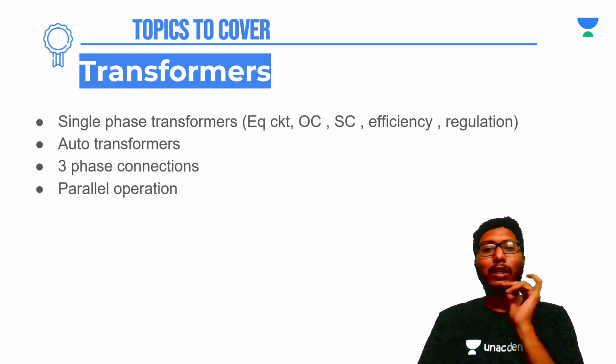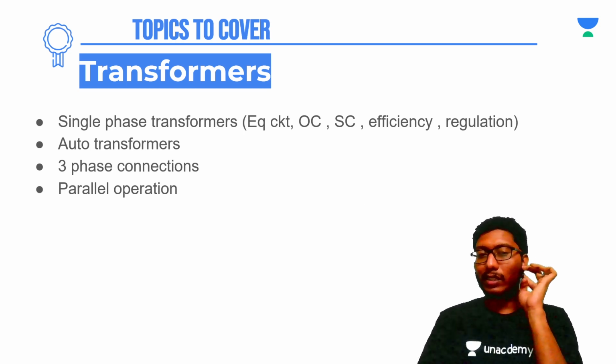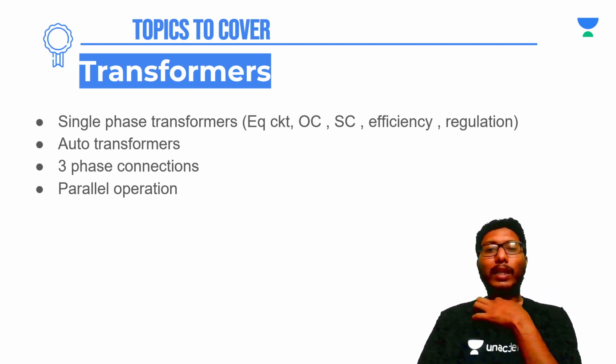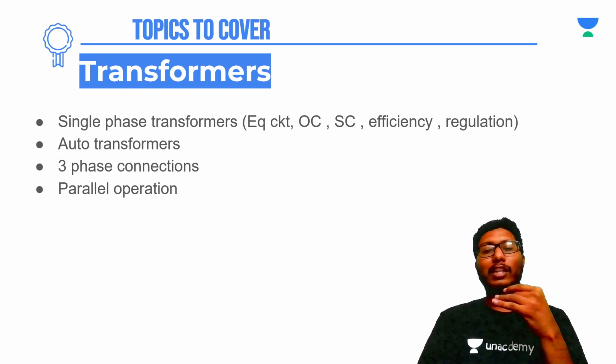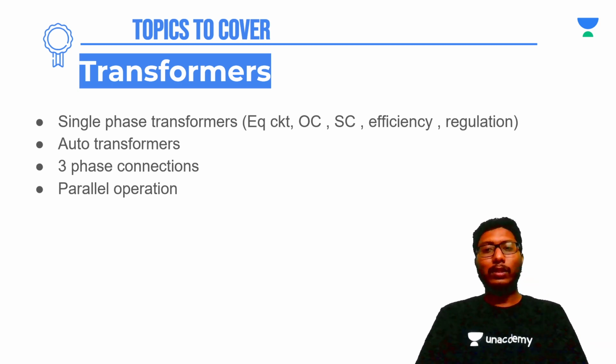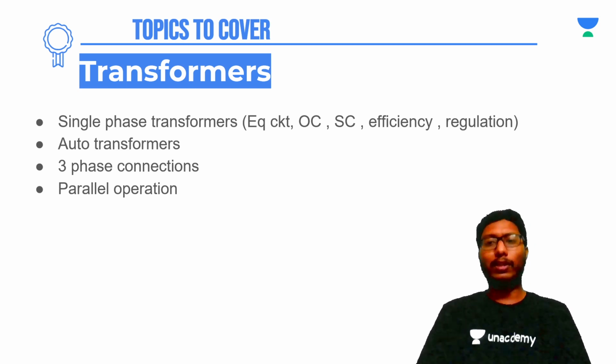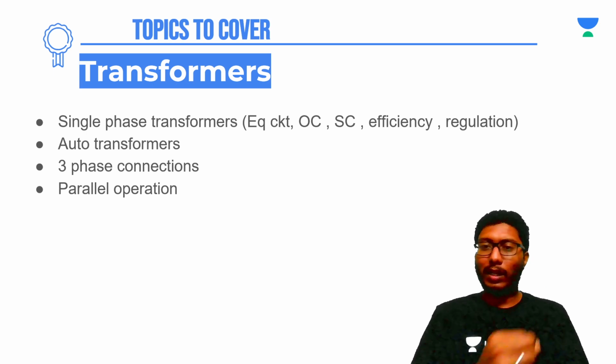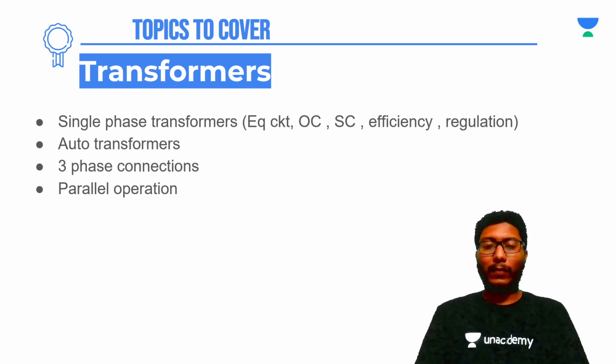So till now we have discussed these losses and everything in power transformer. Now we'll look at distribution transformer. The distribution transformer, unlike power transformer, will have all day efficiency. So whatever losses that we have should be multiplied with the number of hours. The constant loss will be multiplied by 24, but whatever copper loss you have will depend on the